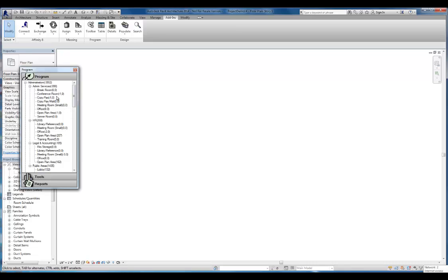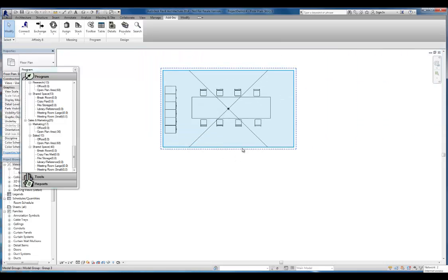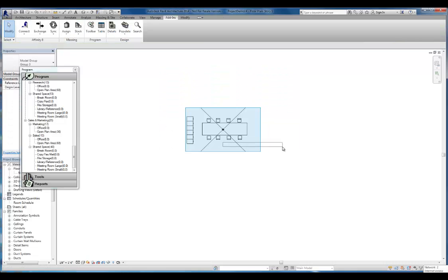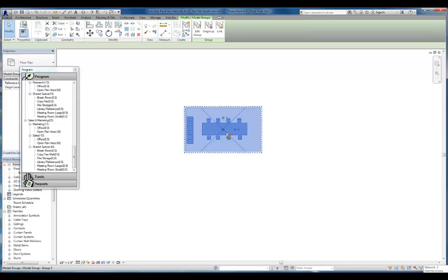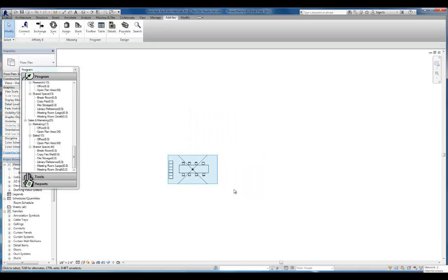And just like I drag and drop, I can drag and drop directly into Revit. Everything is going to come in, and if I have components in it, it's going to come in with components. It's going to be grouped, and I'll get a little error, but that's a Revit thing. It doesn't like the fact that they're grouped. And instead of being surrounded by walls, it's surrounded by room separation lines. The reason we leave it grouped is so that when you drag it out, you can move things around just like you would in Revit as its own little solid piece. So if you wanted to design and figure out where spaces or departments were going to go directly inside of Revit, you can do that with our drag and drop feature here.